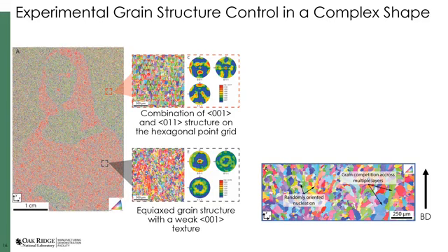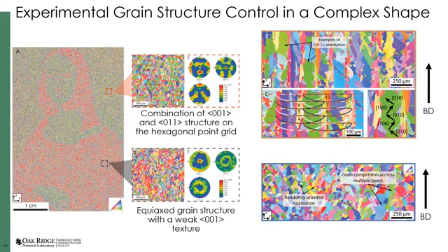If we take a look in cross section, you can see what's going on here, which is that along the center of our melt pools, we get these elongated grains growing up along the build direction. But then in the overlapping regions between melt pools, we have a tendency for these spots to alternate between different layers. And that encourages growth of the symmetry 100 or 010 type dendrite directions to grow upwards in alternating ways, and that encourages this 011 type texture. And this kind of effect has been shown in other alloys and other scan paths as well. So by varying the scan path between these different regions, we're able to achieve this systematic variation in grain structure, even for very complicated geometries.